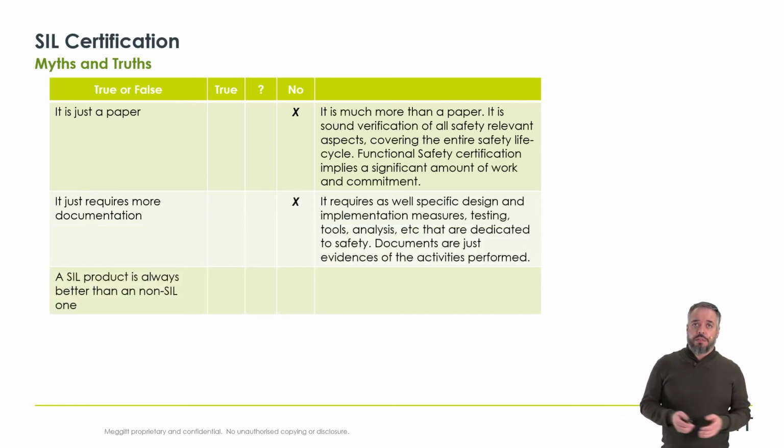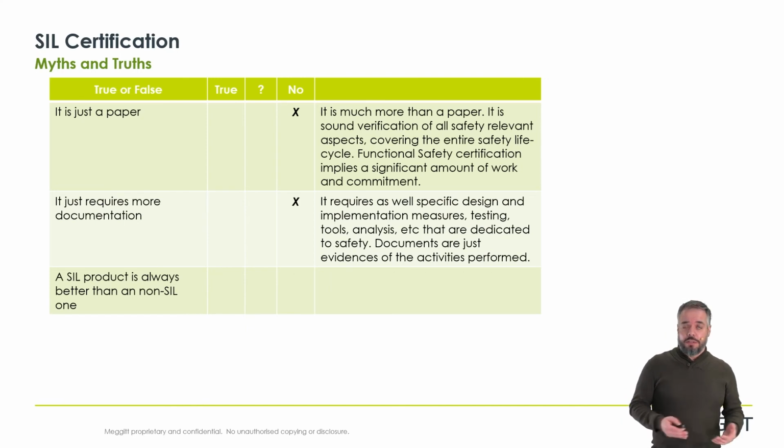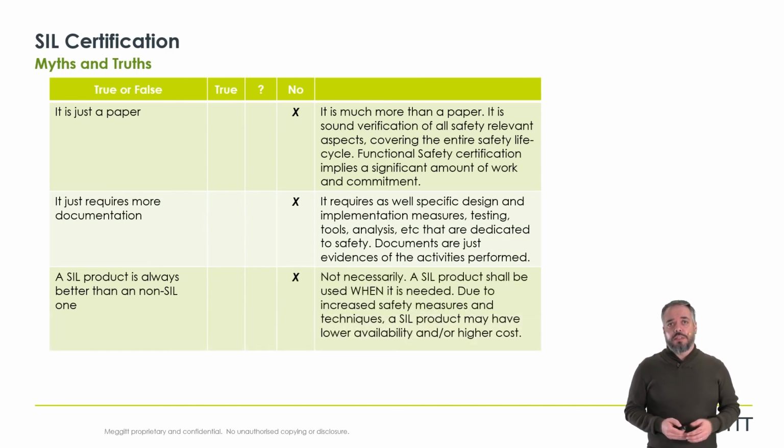A SIL product is always better than a non-SIL one? No, not necessarily. A SIL product shall only be used when we really need a SIL product. The reason is that a SIL product will be more expensive or it will have a higher spurious trip rate, for instance.